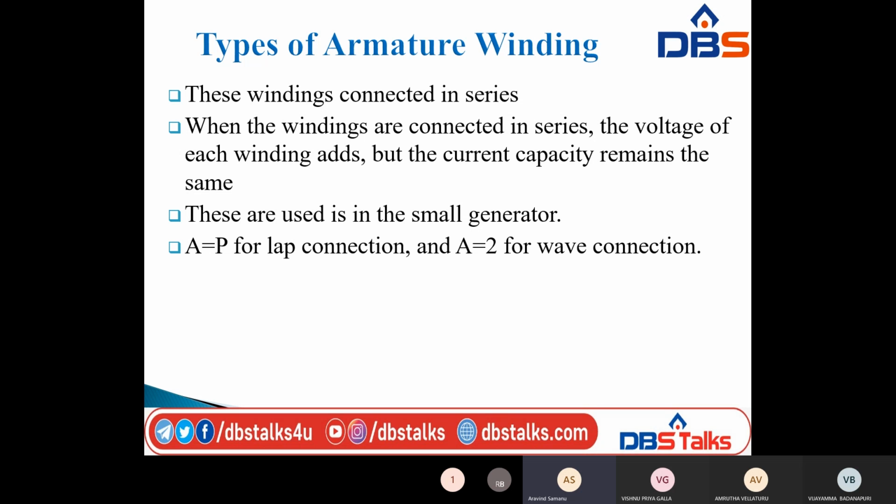So here, when the windings are connected in series, the voltage of each winding adds, but the current capacity remains the same. Here the voltage is adding, current is same. Okay, so these are used in the small generators.